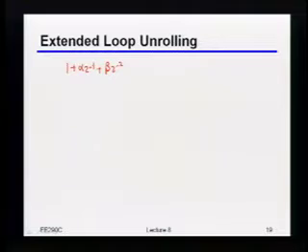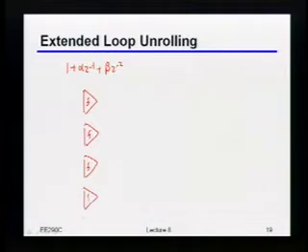Okay, so I think what you're saying will indeed eventually work, but I want to get really specific. I'm a circuits guy, so how many comparators do I need? 4. Yeah, I need 4 comparators, right? Because now I have basically 4 possible data levels that I'm going to be dealing with. Because now I've got 2 previous bits that could have ISI on me, right? So I have to deal with all of the combinations of those 4 possibilities.